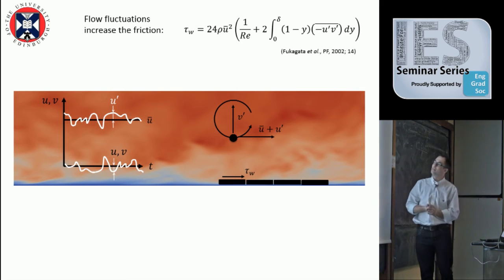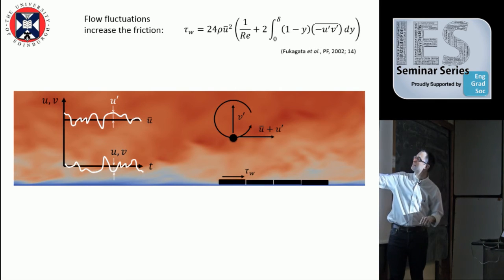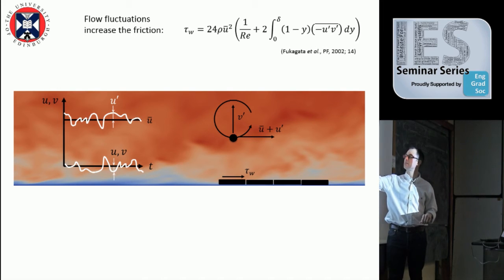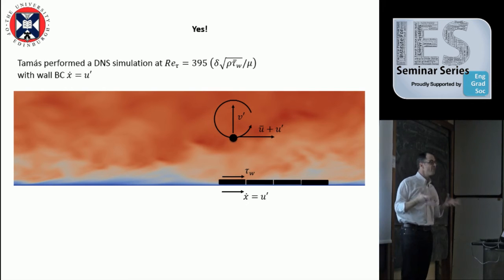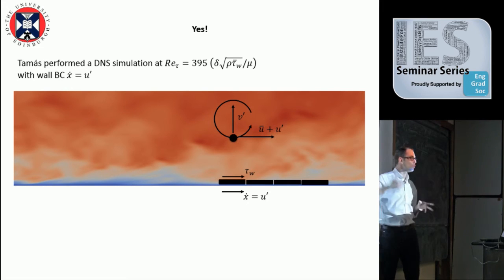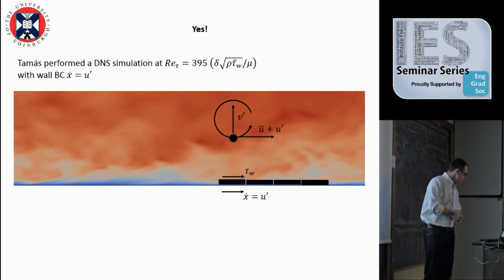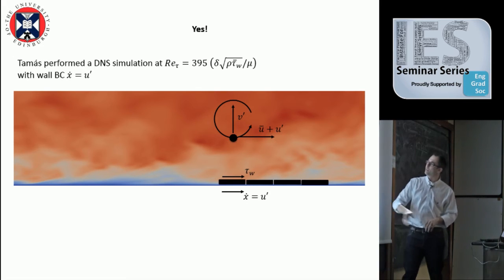Okay. Now, once again, if you have an instantaneous acceleration of the flow here, so instantaneously this is not just the mean, but the mean plus a fluctuation, that means that there is a vortex here which is passing by. So this accelerated flow at this point is related to the fact that you have a vortex, like this one, which is accelerating the flow at this point. So what we really want to do is to manipulate this vortex.